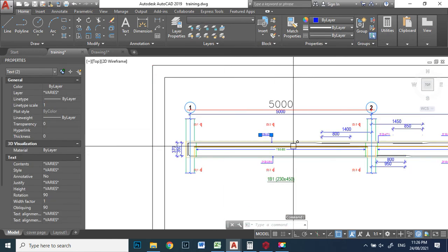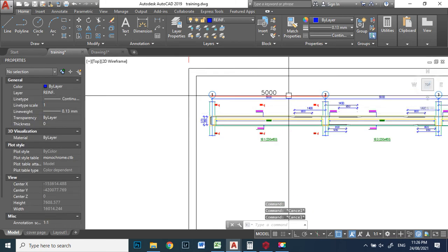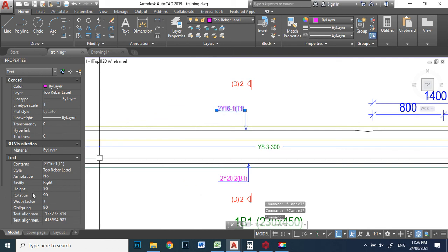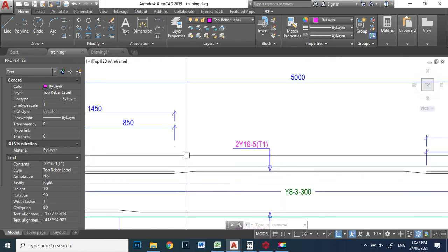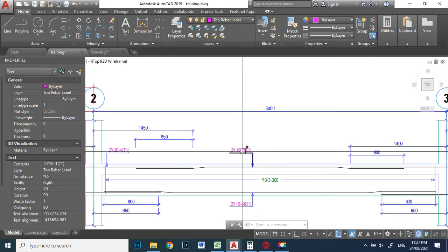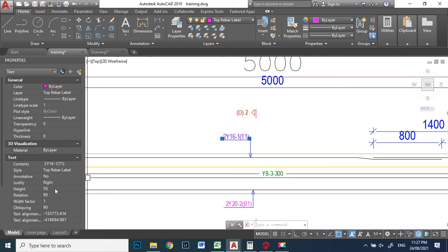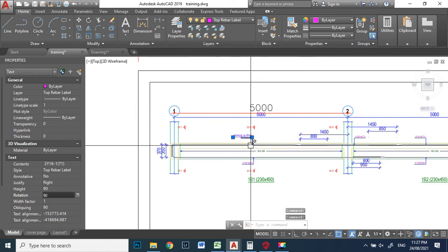Since we've scaled by half, by reducing this by half, the text height is showing 50 because Prota gives you 100. So if you reduce by half, it gives you 50, but our actual height for it to come out good will be 90, which is half of 180.